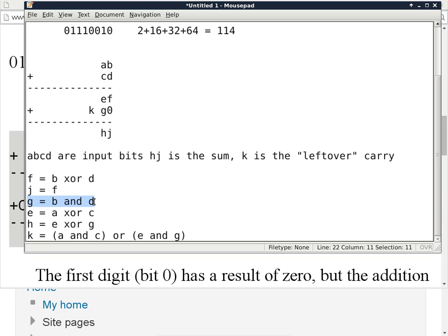Now the most important part is that this half adder has a carry bit, and this one has a carry bit. When you look at how we formulate the equation for K, we know what to do with it, because this carry and this carry need to be ORed. I'm just doing a part of the homework assignment here. That eventually becomes K. Where does F go?